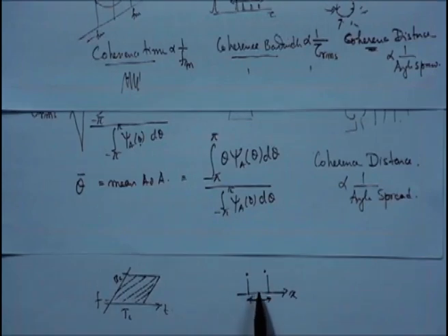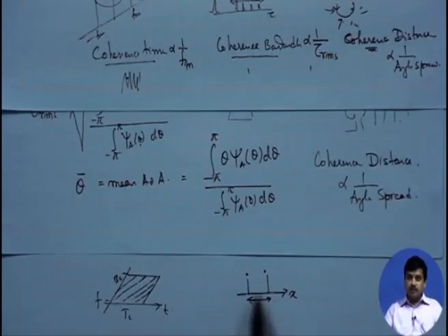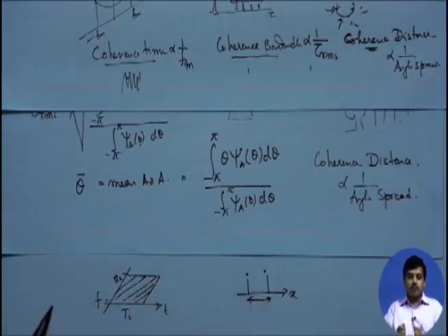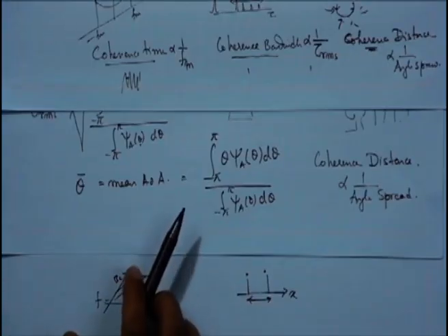Whereas here the situation is not a function of time or frequency, it's with space. So if coherence distance is small, we could place two antennas close together. If we have a mobile which is, let's say, 6 inches or 5.5 inches wide, and the frequency of operation is, let's say, 2400 megahertz or so, we could easily place two antennas on that phone. Whereas at the base station we need to place them far apart, but again the distance would be manageable. This is one of the very interesting things that we have at hand.